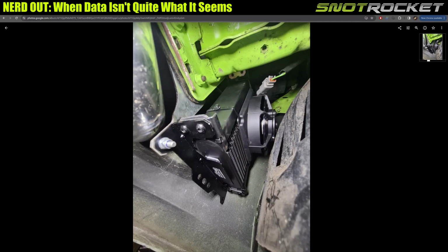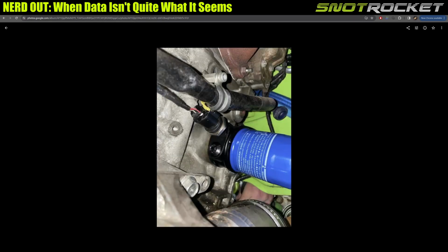Very limited places to put this on the car. So this is here behind the front fog light assembly, and on the right here, this is the inner wheel arch liner. There are some holes in it, some vents, but I'm probably going to open that up a bit more in the future and maybe try and duct this better than what it is. On the back of the engine, this is a sandwich plate from T7 Design. This is what feeds the oil cooler where it's mounted. And this here is a Bosch 10-bar oil pressure sensor combined with a temperature sensor in it. And this is where we're getting the data from.